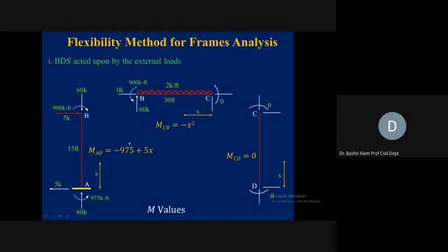So now at joint B, all the member end actions are calculated. The vertical reaction is 60. Horizontal is 0, and the moment is counterclockwise 900, which is coming from 2 times 30 divided by 2. Now this whole member is in equilibrium. All the boundary conditions and everything is met.